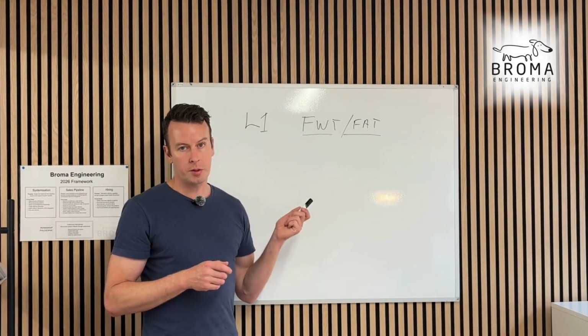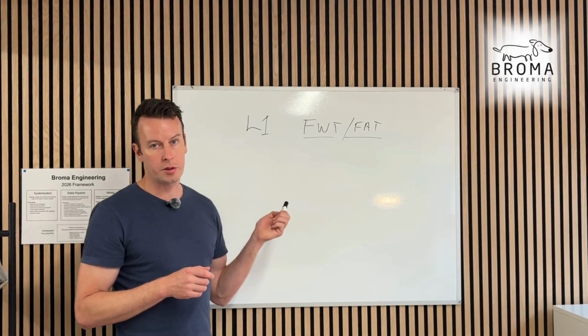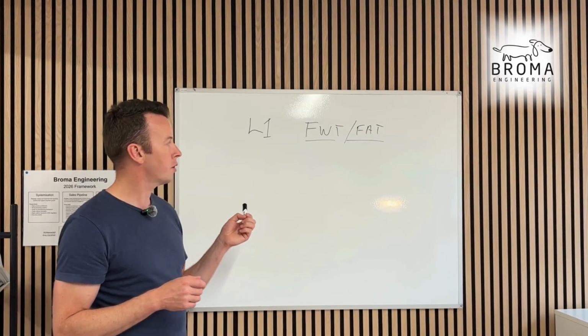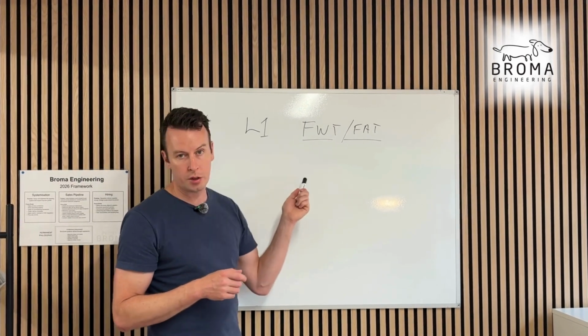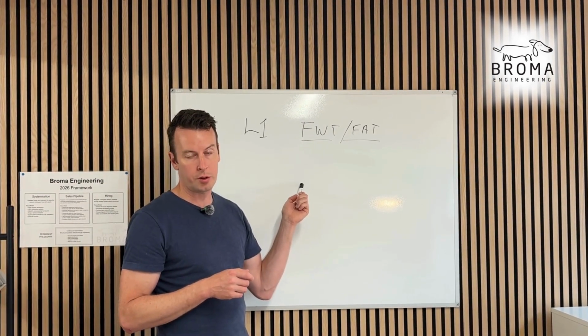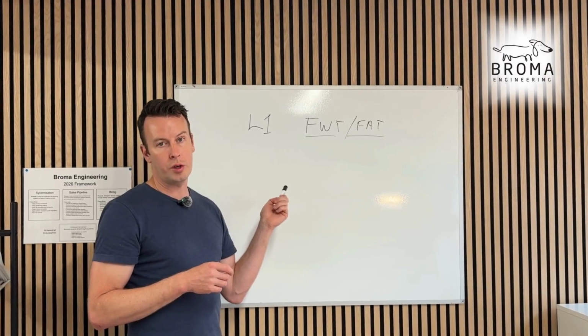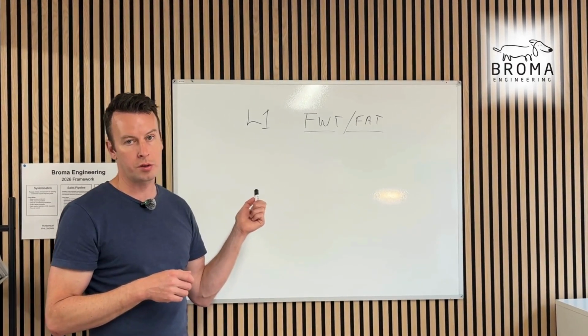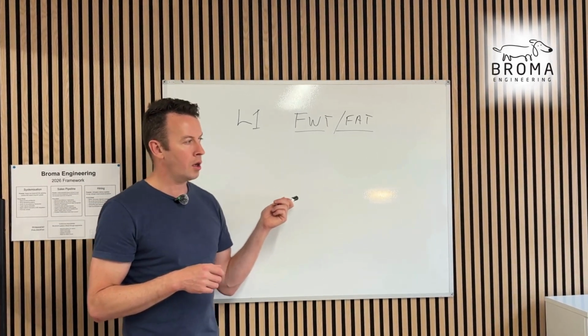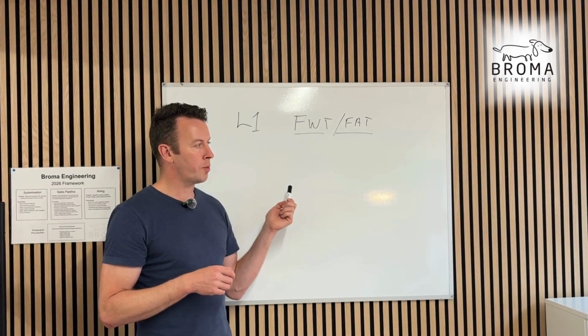I suppose once the FWT is complete, the logistics team need to understand what the shipping terms are, where it is being shipped to, and with these AHUs, they're very big items usually for a data center. So we need to make sure they're not going to hit any bridges or signs on the way. So the vendor usually is in charge of getting it to site and understanding your shipping terms.